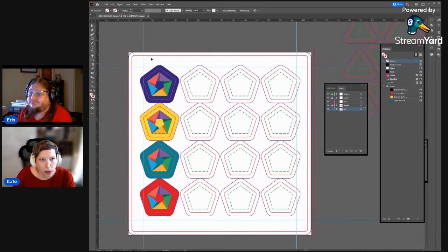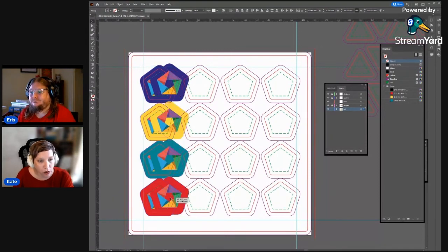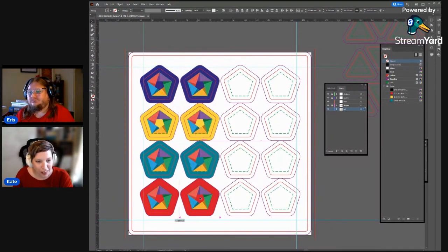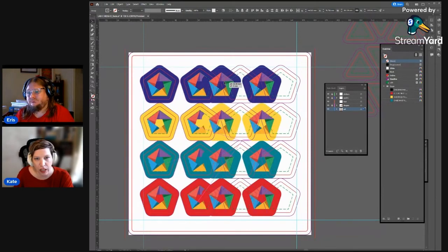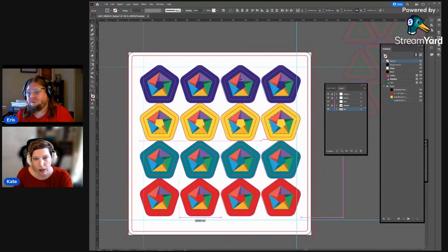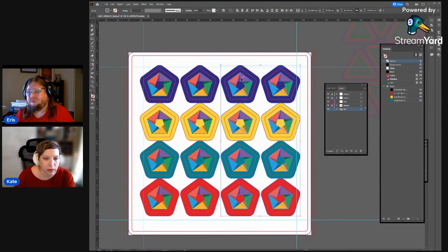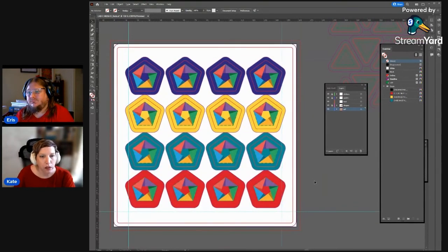So in this case, we've got a really nice, easy layout, which is basically I'm going to select all of them, hold Alt and Shift to bring it across like that. And then because I don't want to have to do it 2 more times, I'm going to do all of those again. But because something is snapping to something else, I'm going to use my mouse. And there we have a custom punch board layout. Ta-da! That has worked really well.